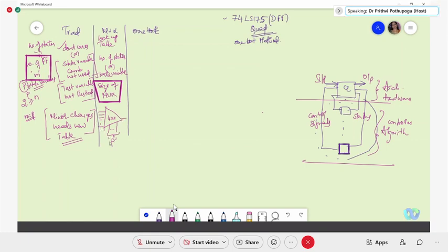Now, here we have the flexibility of adding many other states to the unused inputs in the mux. But the size of the mux available commercially is limiting us for the mux approach. Maybe we said 32 states, not more than that. That 32 itself is a bigger complex design when you take it as an ASM. 32 states in your ASM is itself the biggest complex design. So maybe the mux method is the most used method.